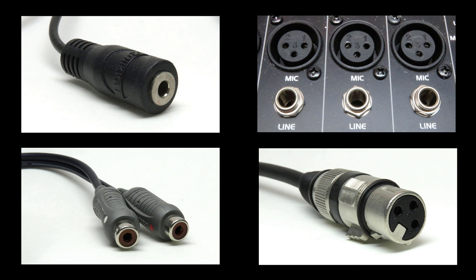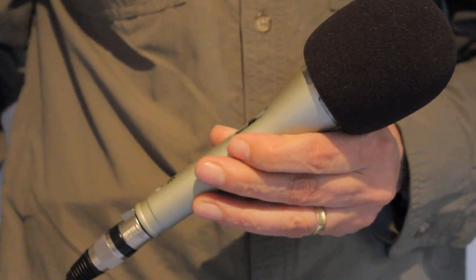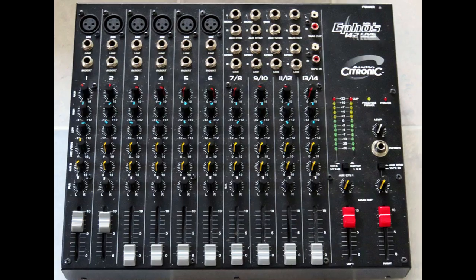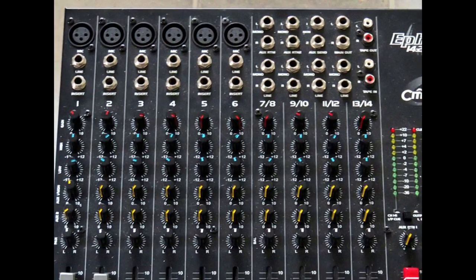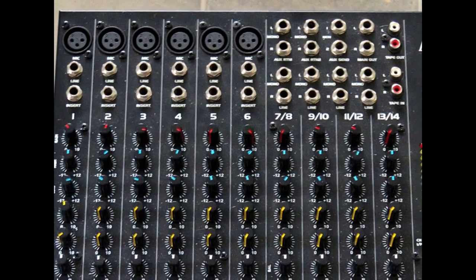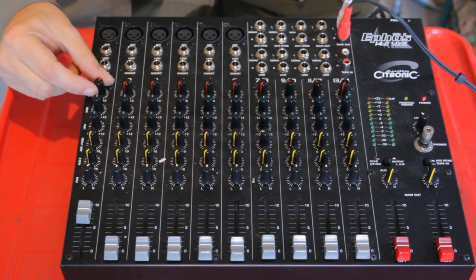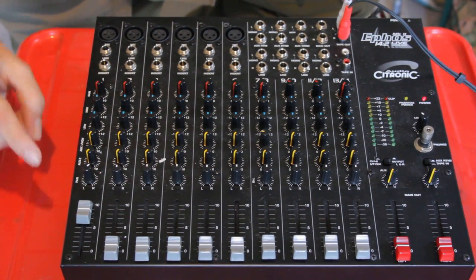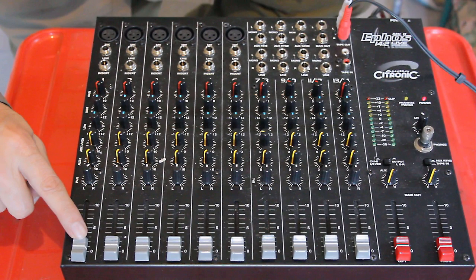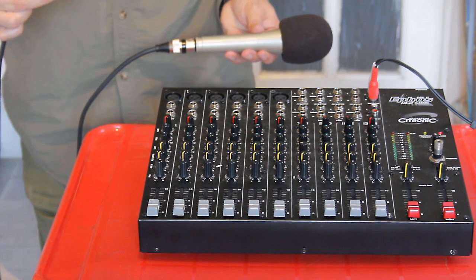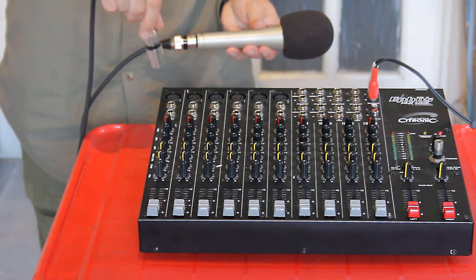Right, we've just connected one end of our XLR cable to our microphone, and we were about to connect the other end to the mixer. However, before connecting any source to the desk, there's something very important that we need to do. Set the gain knob and the fader for the input channel concerned to minimum. This avoids the occurrence of any nasty bumps or thuds through the system when we make the connection. Now the connection can be made safely to channel 1 in this instance.